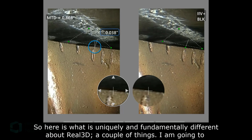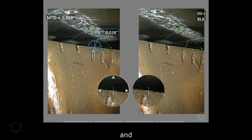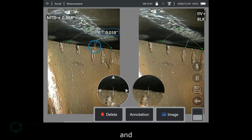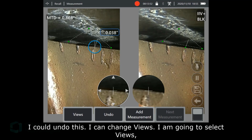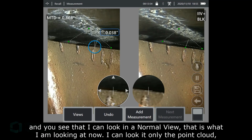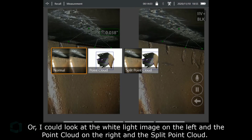A couple of things. I'm going to double tap the right hand portion of the touchscreen, and I'm going to now toggle the soft keys, and I could undo this, I could change views. I'm going to select views, and you see that I can look at my normal view. That's what I'm looking at now. I can look at only the point cloud, or I can look at the white light image on the left and the point cloud on the right in the split point cloud.